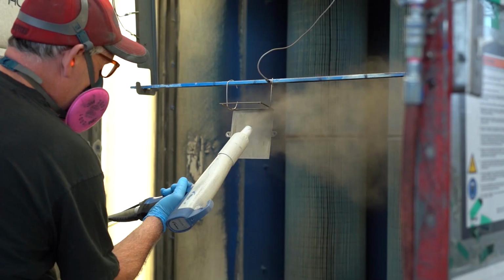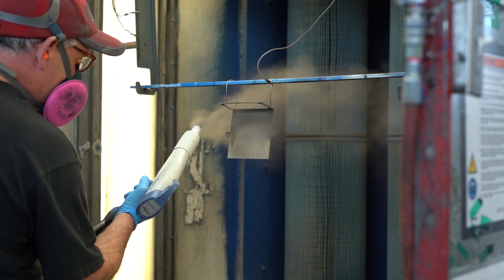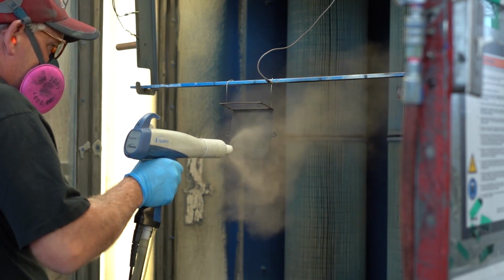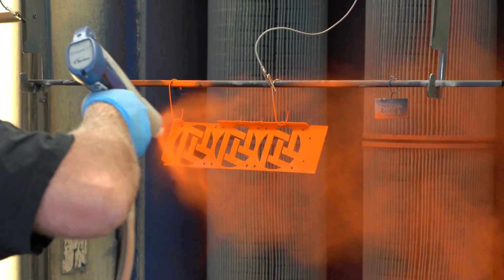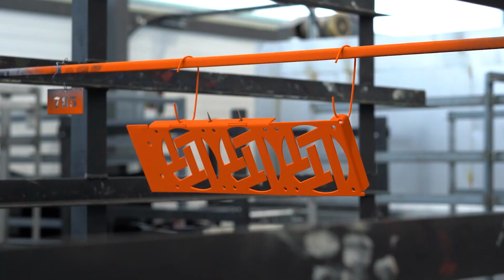Then we have one of my personal favorites, powder coating. Powder coating is an excellent way to add corrosion resistance, durability, and protection to your part. We offer a wide range of powder coat colors and texture options, which will give you a vibrant, professional look that will make your parts stand out. Remember though, if you are looking for electrical conductivity and want to opt for powder coating, masking either select areas or the entire inside of your enclosure will be essential.